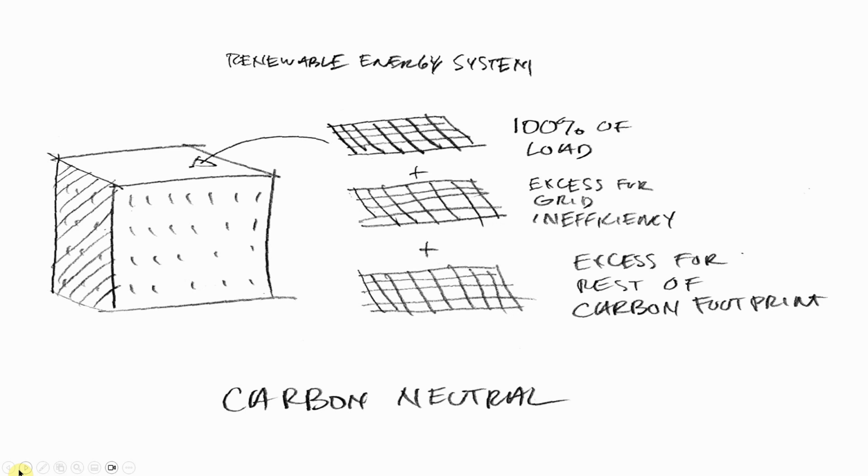And so the idea here for carbon neutrality from energy production goes as follows. First, we have to reduce our loads, like I said. And then there's a little bit of trickery here, but it's not really, because it's very true until everybody is producing renewable energy, we'll have to find other ways to reduce a project's carbon footprint all the way to carbon neutrality. But right now, this is how it works. If your first goal is to make 100% of the energy your project requires on site or through some kind of microgrid or cogeneration, doesn't have to be photovoltaics, whatever, that's called site net zero energy.